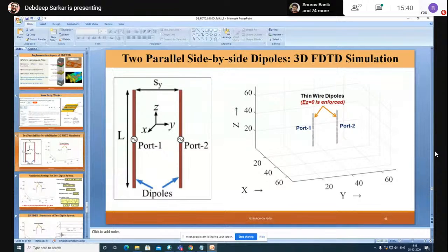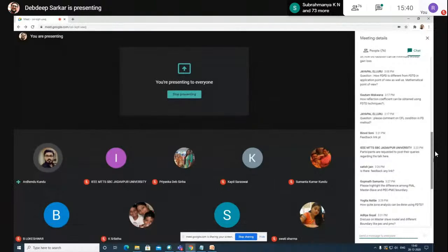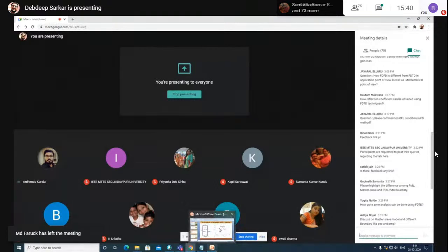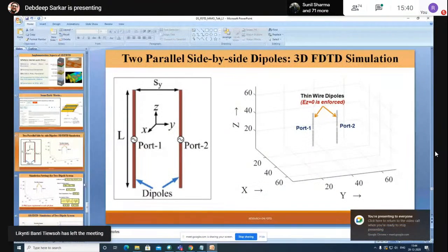Yeah. Okay, thank you. One small question from my side: in CST Microwave Studio, we can find that in the boundary there are 4 PMLs with 0.0001 reflection coefficient, in my version. So whether individual PMLs have a reflection coefficient of 0.0001 and 4 such are used together, so that the reflected wave is almost nil.